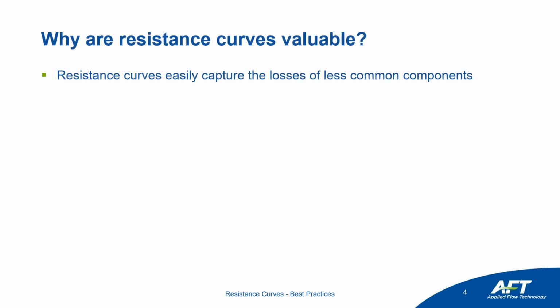So why are resistance curves valuable? Why might you use that instead of defining a valve in terms of CV or a loss factor in terms of K? It's because resistance curves are very versatile and they have a lot of flexibility to capture losses of very different components.